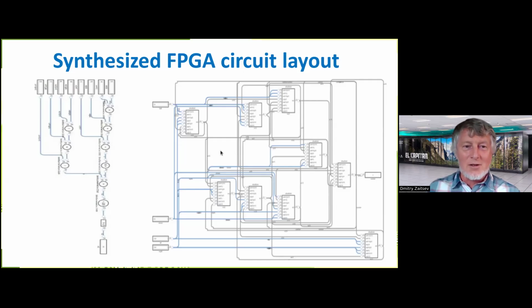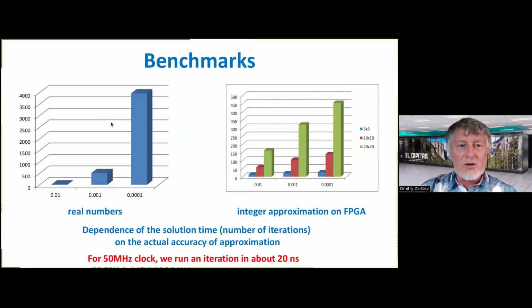By the way, this Tang Nano FPGA with 9 kilo LUTs costs some 10 pounds, and it has a frequency of 27 megahertz, which is rather good for initial training. We are using this kind of FPGA for teaching Rolls-Royce apprentices, who are very satisfied with this rather simple and powerful instrument. Finally, we obtained a series of benchmarks.